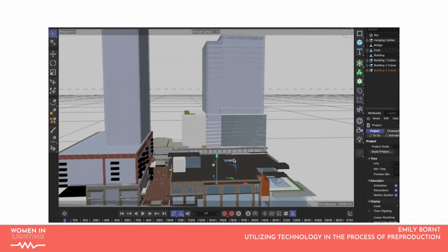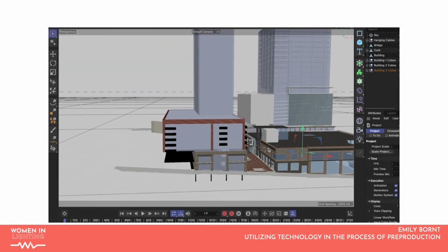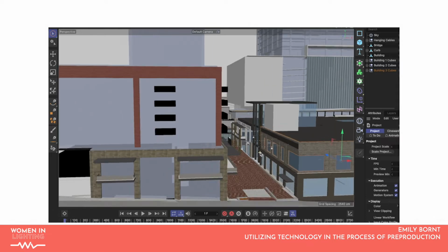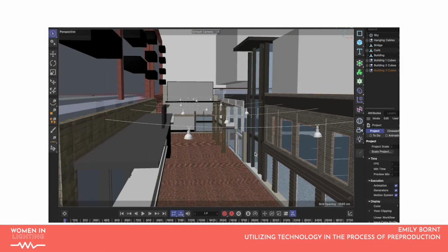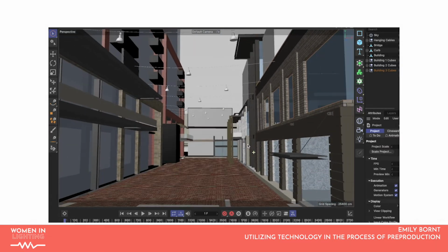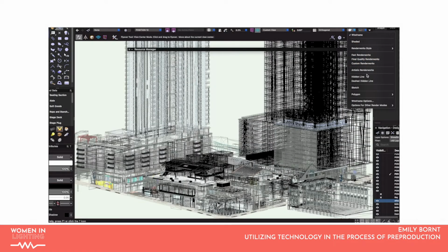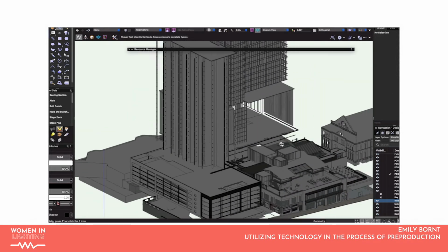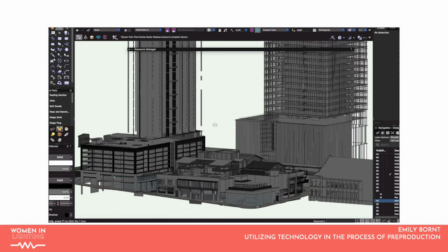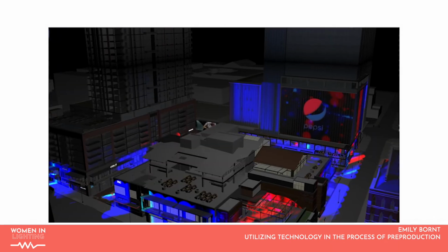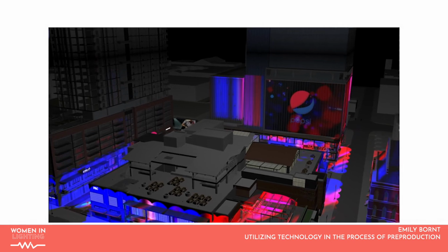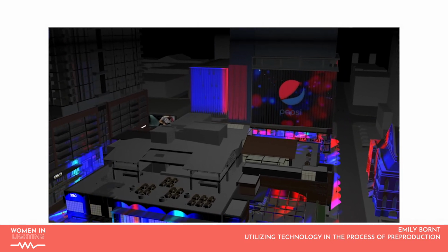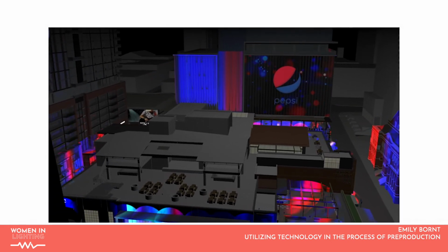Over the course of a few weeks, I was able to get the file size from 650 megabytes to 45 megabytes, making it much easier to export to Vectorworks and grandMA 3D. From there, we started laying out lighting positions without the software crashing or lagging. It also made previs and programming quicker because the software had fewer polygons and surface reflections to calculate.